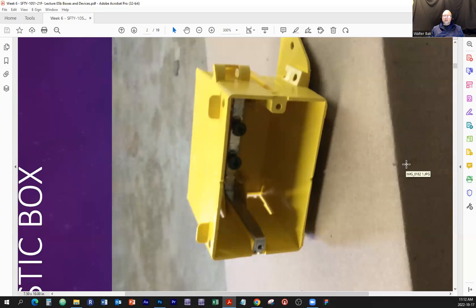And remember what the difference between bonding and grounding is? Grounding is if there is a terminal or a connection point that runs to the ground, something that's called a true ground, and it's connected with one uninterrupted piece of conductor. That means it's grounded.